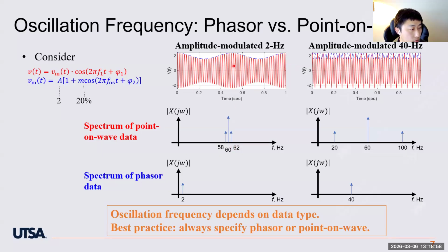So the three plots in the same column represent the same behavior of the system, but in different domains, time domain and frequency domain. But if you look at different data sources, you may see different frequency components. Right now it's totally fine because most of the oscillation monitoring applications are based on PMU, so there is not much confusion.